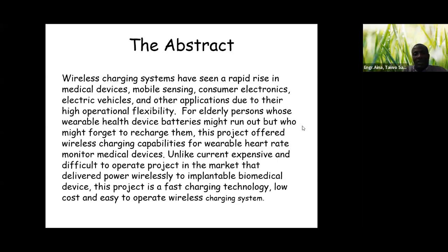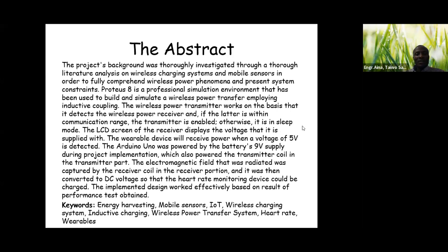And not that alone, the final stage now. The project background was thoroughly investigated through a thorough literature analysis on wireless charging systems and mobile sensors, in order to fully comprehend wireless power phenomena and present system constraints. Proteus 8 is a professional simulation environment that has been used to build and simulate a wireless power transfer employing inductive coupling. The wireless power transmitter works on the basis that it detects the wireless power receiver, and if the latter is within communication range, the transmitter is enabled, otherwise it is in sleep mode.